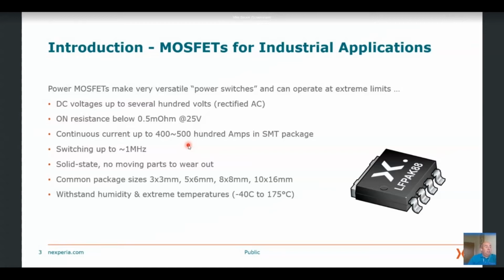And with switching speeds, certainly in the hundreds of kilohertz, getting towards a megahertz in the extreme. They're solid state, so it's a piece of silicon inside. There's no moving parts, unlike a relay or a circuit breaker. There's nothing there to wear out apart from the silicon itself.